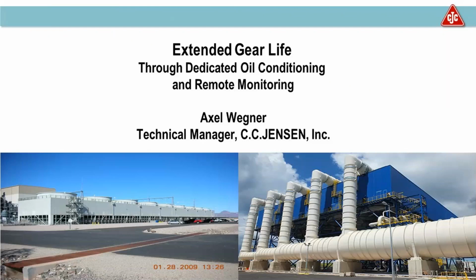Because I do understand that initially you should get some wear and your iron content might be a bit higher than it should be. But after how many hours should it be stabilized if you just have the normal inline filters and you are not running a kidney filtration system?